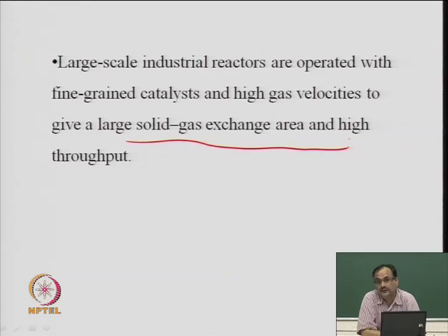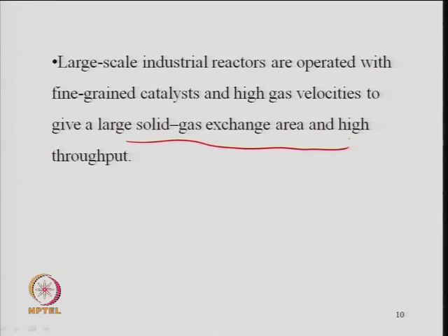So, you have to design the size of the reactor, and I will discuss that in subsequent lectures, but the design of the fluidized bed reactor in terms of the residence time distribution is very important. It means how the temperature, if it is an exothermic reaction, or the concentration down the length of a bed changes, that is very important. So, we need to look at a separate hydrodynamic study and a residence time distribution study by using some tracers for the fluidized bed,